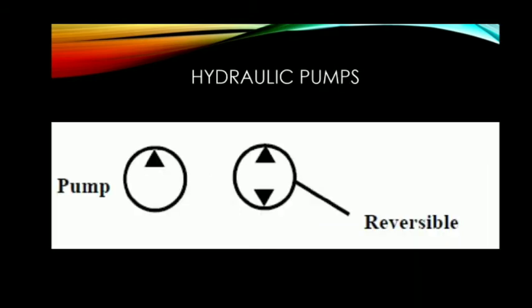Hydraulic pumps. The pump converts the mechanical energy of its prime mover to hydraulic energy by delivering a given quantity of hydraulic fluid at high pressure into the system. Generically, all pumps are divided into two categories, namely, hydrodynamic or non-positive displacement, and hydrostatic or positive displacement. Hydraulic systems generally employ positive displacement pumps only.